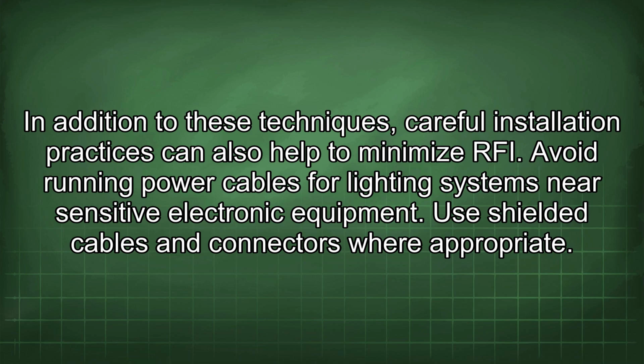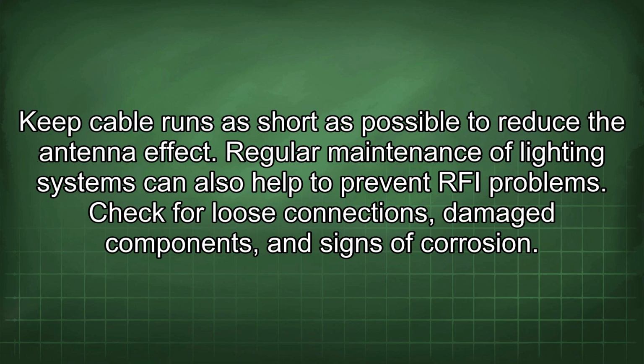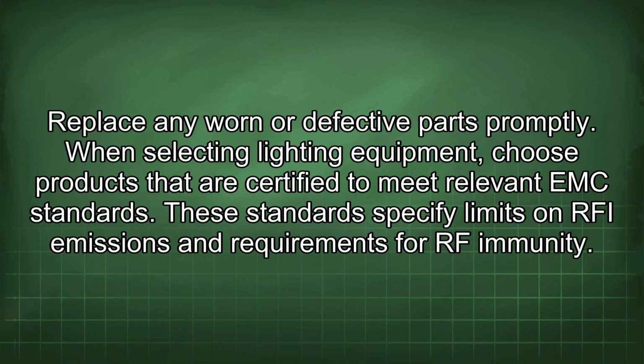Use shielded cables and connectors where appropriate. Keep cable runs as short as possible to reduce the antenna effect. Regular maintenance of lighting systems can also help to prevent RFI problems. Check for loose connections, damaged components, and signs of corrosion. Replace any worn or defective parts promptly.